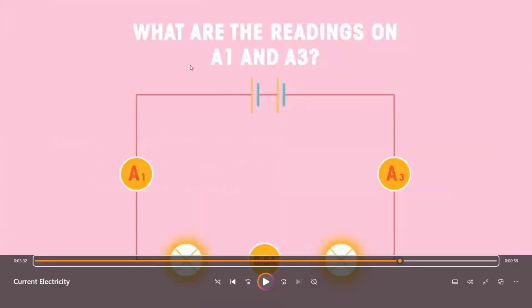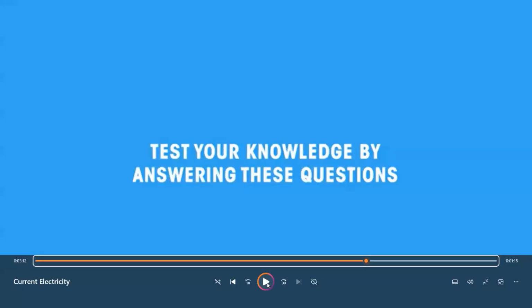Now we have a circuit, all of it connected in series. We have that A2 is 0.5 ampere. So this means that all the ammeters in series must have the same reading. So A1 must have 0.5 ampere and A3 must also have 0.5 ampere.